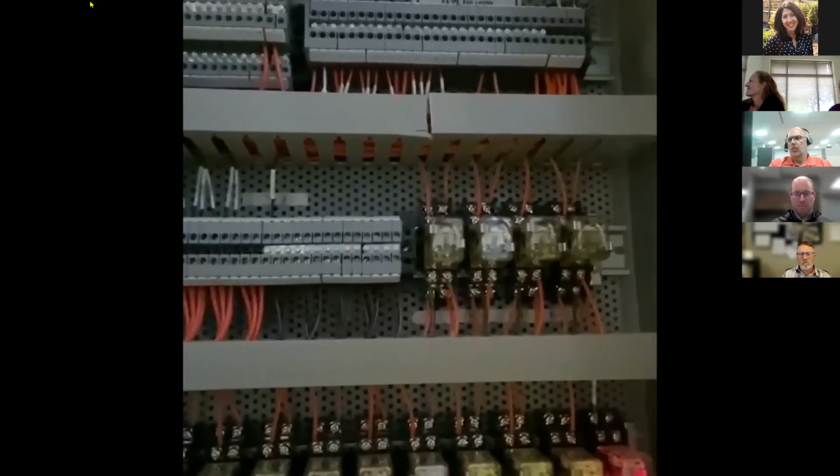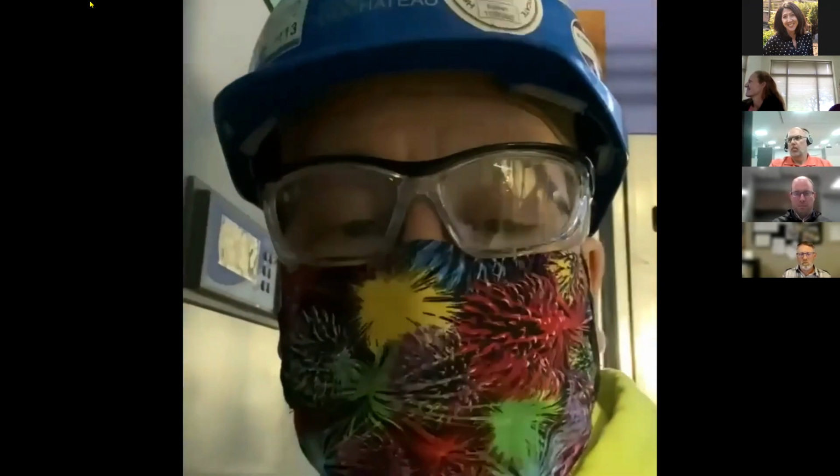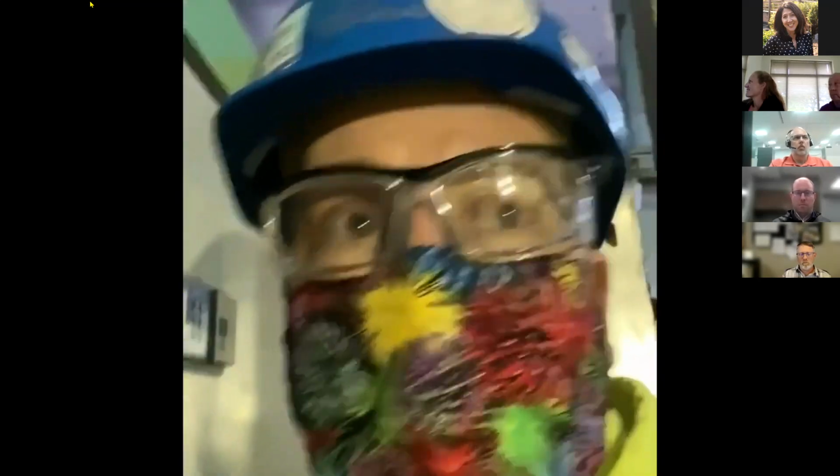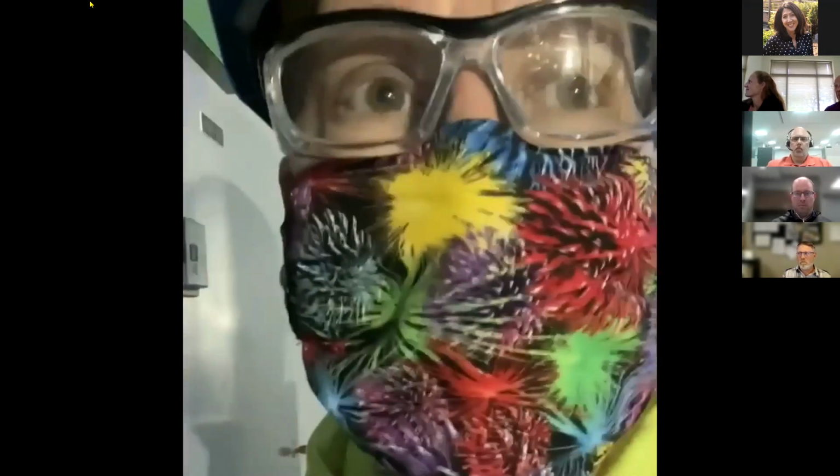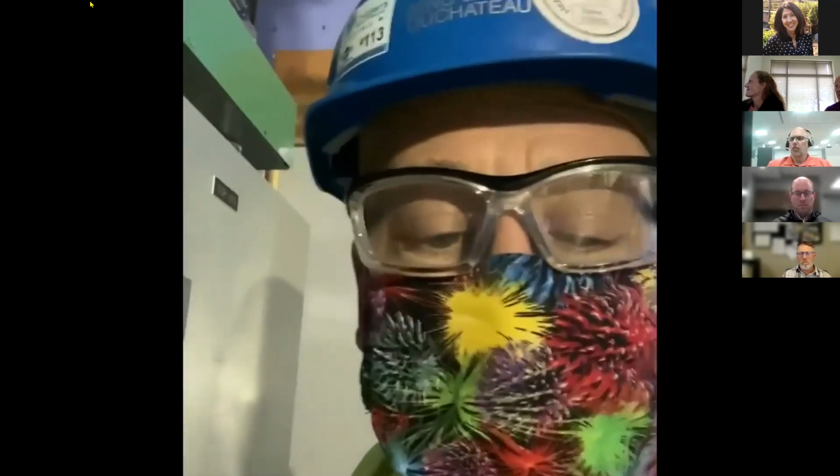The good safety light saying that I'm good is there. And if I stop talking, you can hear actuators starting to move and everything's ready to roll. So that's a way of testing our vertical steam face and bypass coils. Roger that. Any questions? So that was a vertical steam face and bypass damper, or coil face and bypass damper.